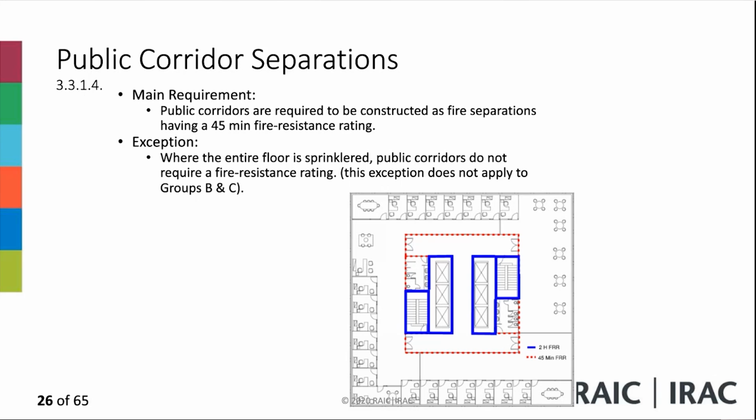But there is an exemption to that. If a story is sprinklered, so I'm reading sentence 3, if a story is sprinklered throughout, not halfway or a portion of it. Now I'm not talking about a floor area anymore. Remember before we saw a provision for janitor room where the floor area is sprinklered throughout. In this case, we have the whole story sprinklered throughout.